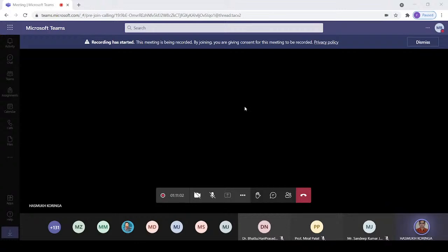It will open an editor window where we can have different ports. Let me insert the port, node or bus, and by finding the node and bus, let me find from our module traffic underscore control. So it will list out the different ports that we have in the traffic underscore control module. Select all the ports and okay.